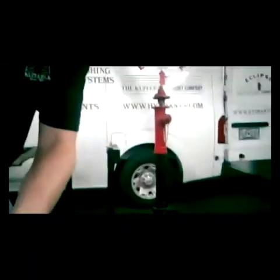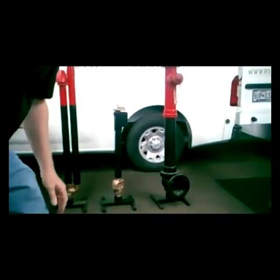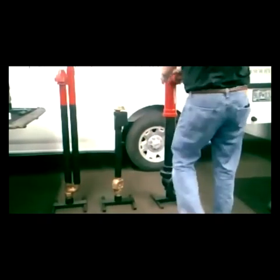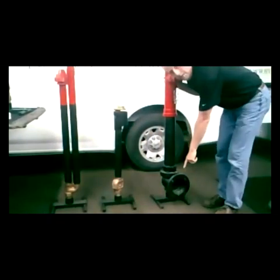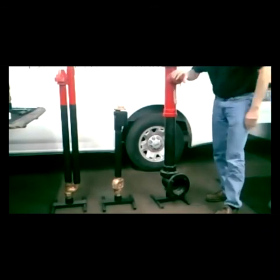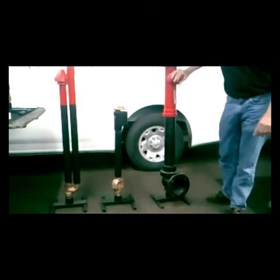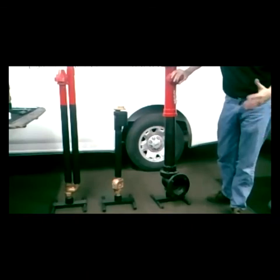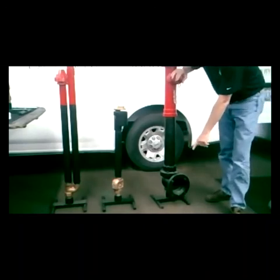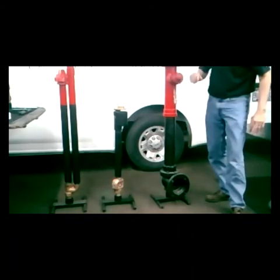The number 2, again, is a post hydrant that we've been making for a long, long time. This one actually has a 4-inch MJ. So again, I have my inlets anywhere from a 2-inch up to a 4-inch MJ. Operating rod with a plunger design, 2.5-inch NST nozzle. We can do other sizes on the inlets and on the nozzles. So anything up to a 2.5 NST, if you want a 3/4-inch garden hose, if you want a 1-inch, we can do anything you like on the outlets. Inlets anywhere from a 2-inch FIP all the way up to a 4-inch MJ and in between. So a lot of choices with this hydrant on inlets and outlets.